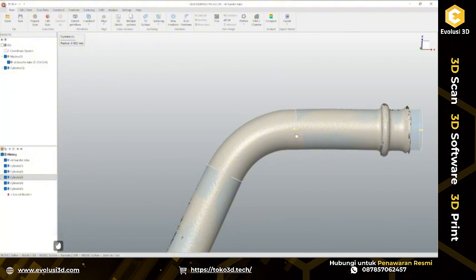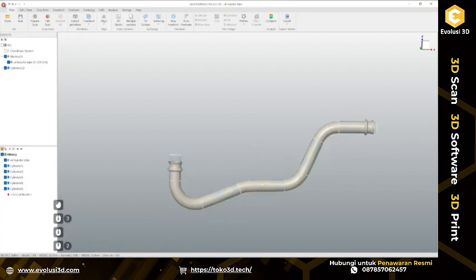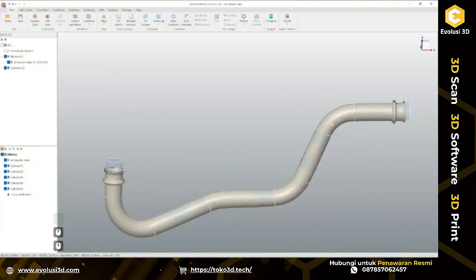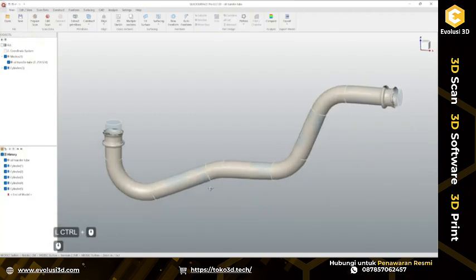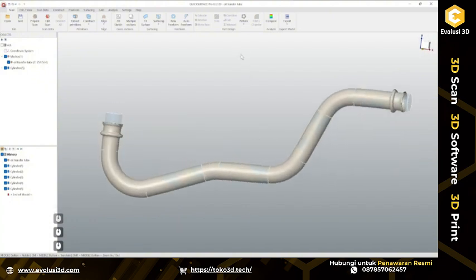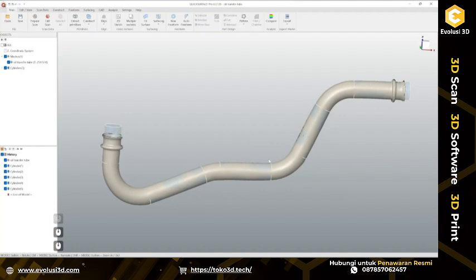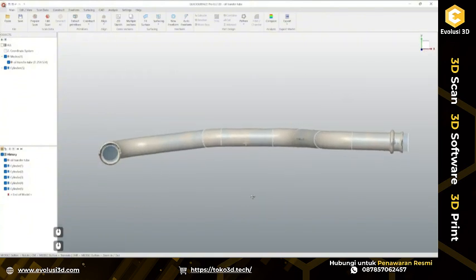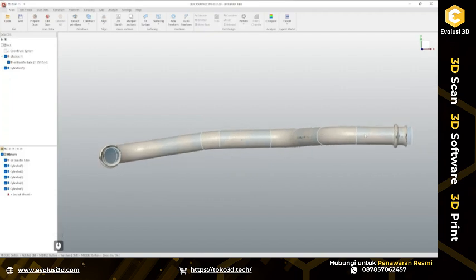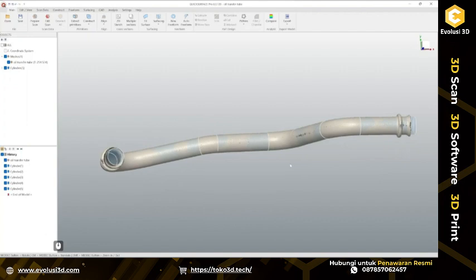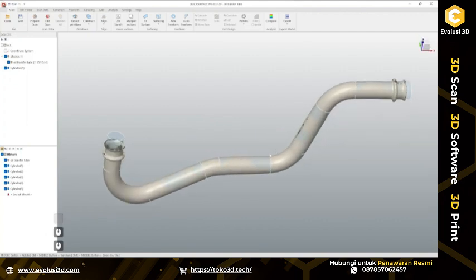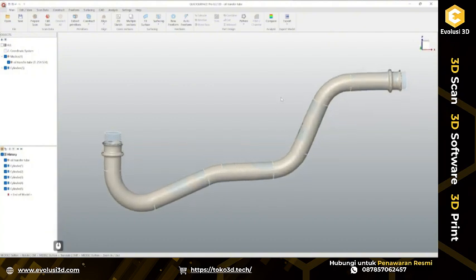First, there is always one thing to remember: depending on our bending tools, typically these bends are slightly squished, so we don't expect to see a perfectly great deviation analysis for these regions. And depending again on the same bending tools, all these pipes can be slightly twisted during bending or warped somehow, so it's not just a planar bend. In those cases it makes life slightly more complicated, but for general purposes we want to recreate this as a normal CAD model that we want to use later for manufacturing, for example.